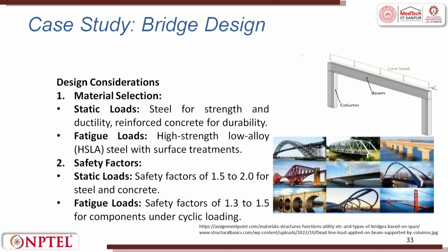The design considerations when we are trying to do a bridge are: static load, steel for strength and ductility, reinforced concrete for durability. Fatigue loads, high strength low alloy steels with surface treatment is always considered for fatigue loads. Then safety factors: a safety factor of 1.5 to 2 for steel and concrete is considered. Fatigue life: a safety factor of 1.3 to 1.5 for components under cyclic loading is considered.